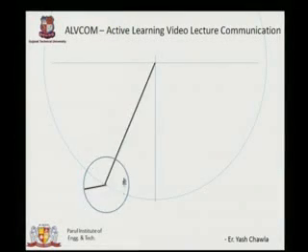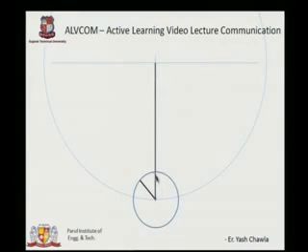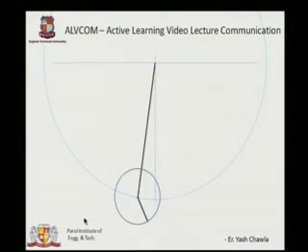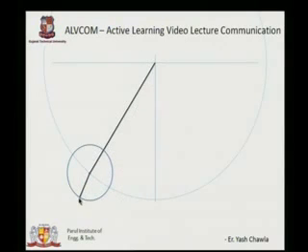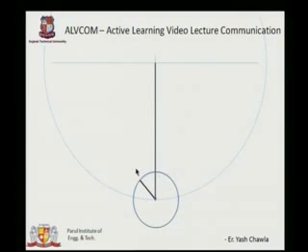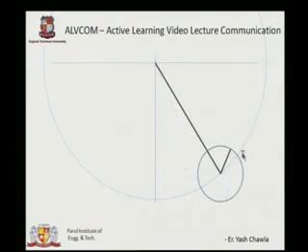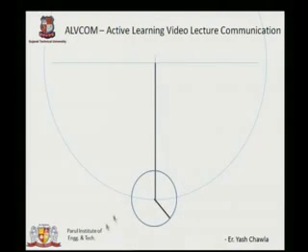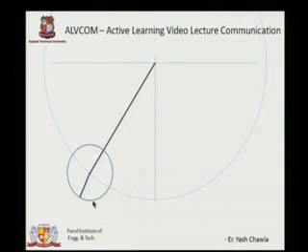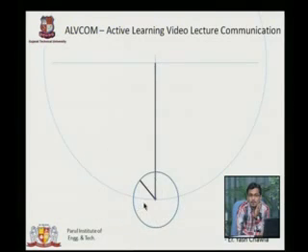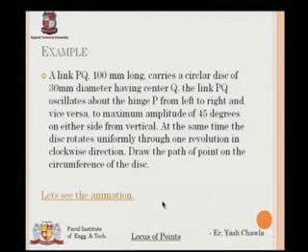The question is getting more clear. The length of this rod is given. This is hinged here at P. This is PQ. This disc is rotating clockwise while the rod moves from left to right. So what the question says is, from this point, we'll let it come to the particular position and we will see. This is the beginning position. From this the disc is rotating clockwise and it is oscillating towards the right. From here till here the disc rotates through 180 degrees and the rod travels 90 degrees. So this is the particular point for which we have to trace the locus. Now it won't be a simple circle because this thing is moving, and this is just showing the circle on which the crank is moving about this particular point. Okay, now let's get down to drawing the figure.